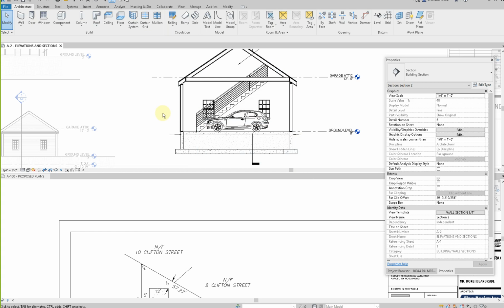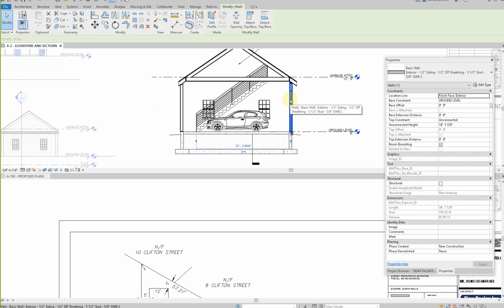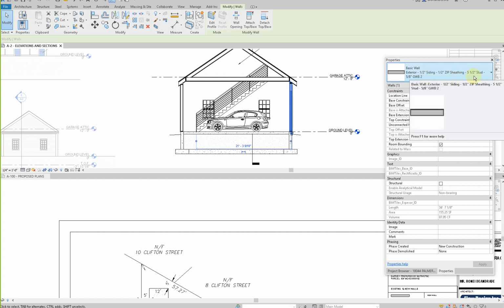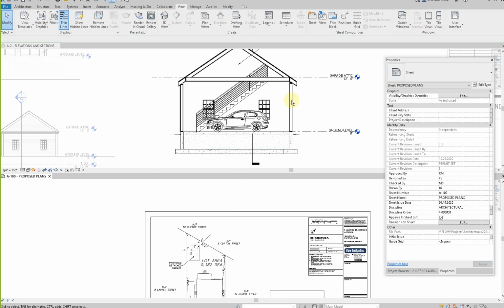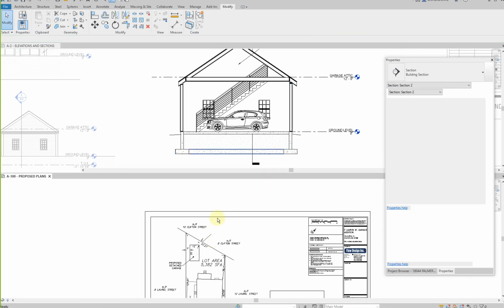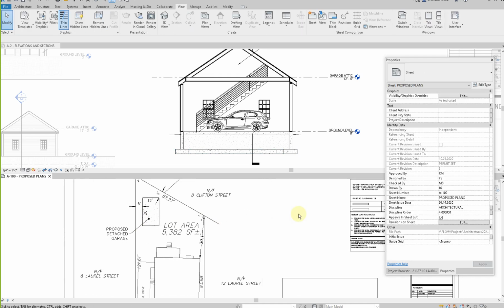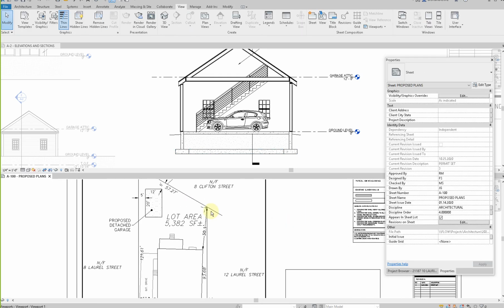So what was the name that you gave to the walls? You said that in New England they're normally made out of what? So half an inch siding, half an inch zip sheeting, 5.5 inch stud. So these are the ways you would do the wall. Okay. We already have a wall like that. So in fact, I'm going into this model of this other project, but we already have a wall. So you're gonna look for a wall that will have the typical construction. Now this is another session, and I'm already 50 minutes into this, so I could have another session on walls and how to make walls and all that stuff. But for now, just bear with me.